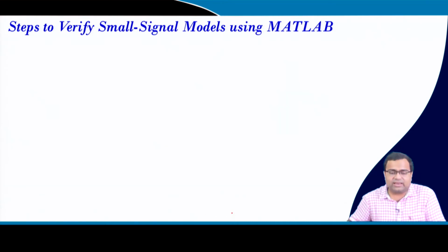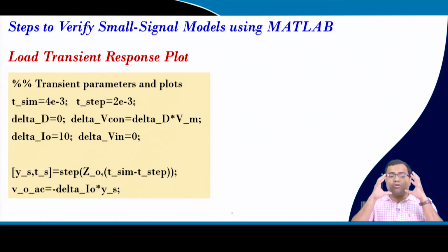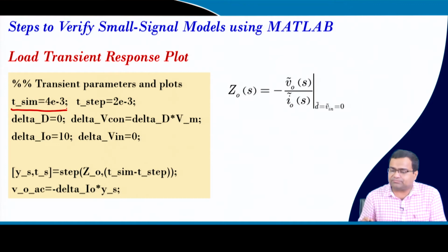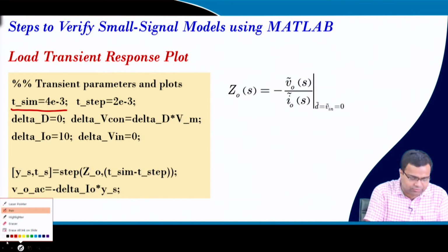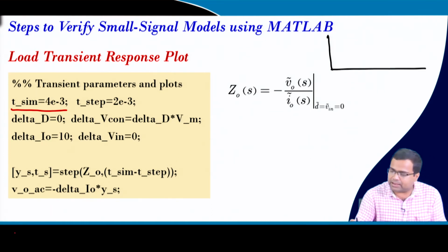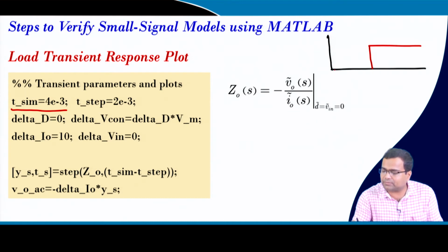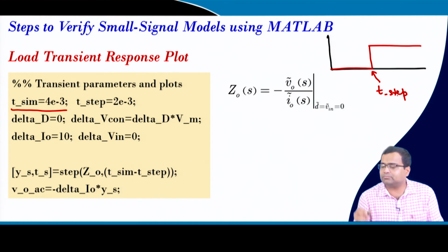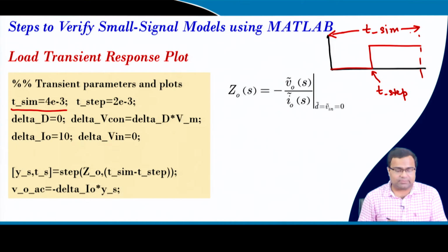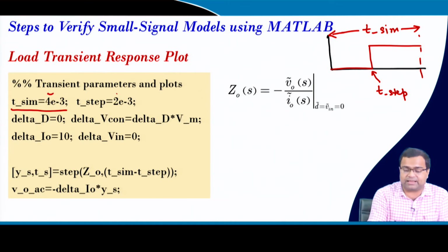Next, we need to check the load transient response, because we need to verify it. So here is the total simulation time. If I want to simulate, I will apply the load step at this time. This is my t step time, and this is my total simulation time, which I am calling t sim. So the total simulation is 4 millisecond and the step is applied at 2 millisecond.